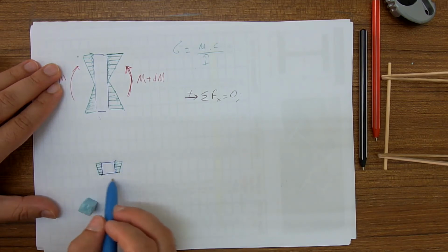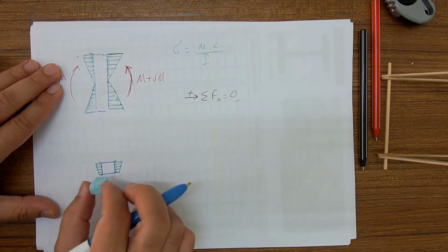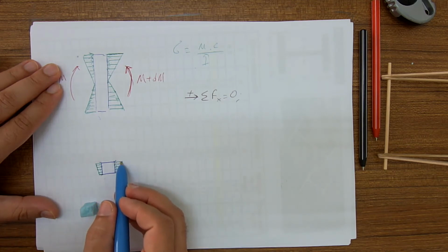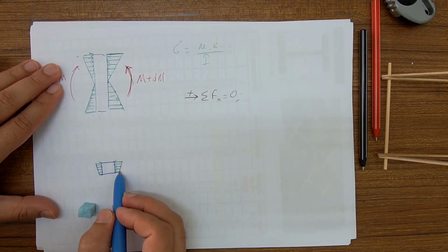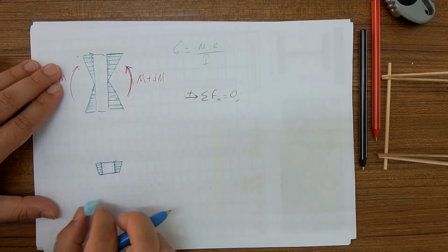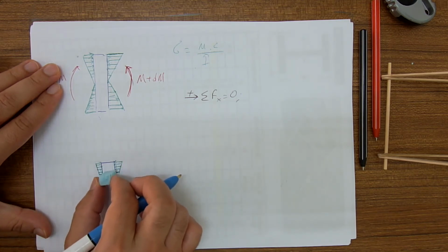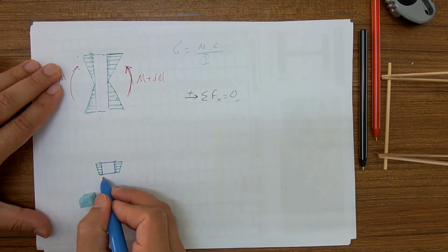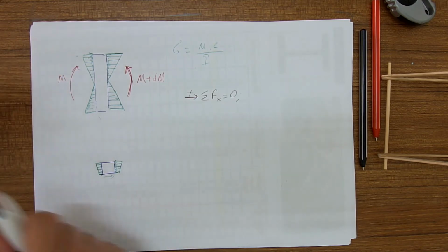If these were the only stresses, then this structure would not be in equilibrium, because of the magnitude of the stresses, you see, for each corresponding arrow, those on the right is larger. Therefore, this segment would move to the left upon these loadings, upon these stresses. But it doesn't happen. What happens is there is a shear stress just below this section.